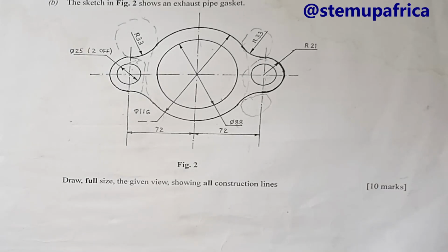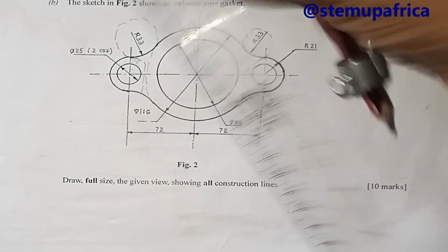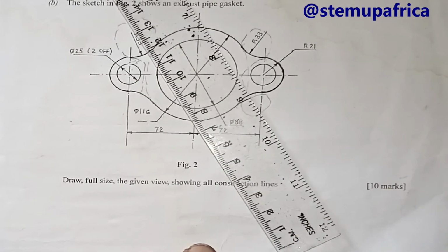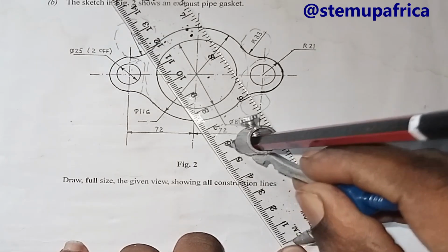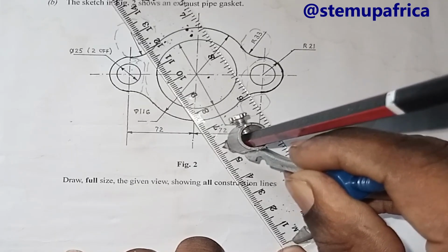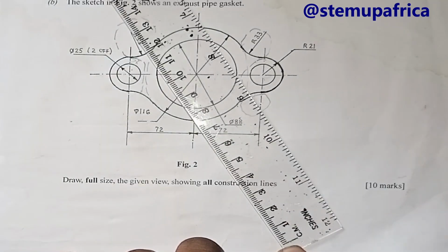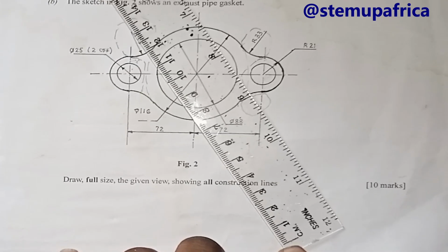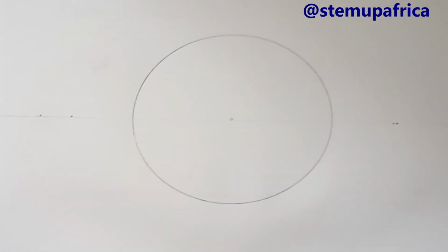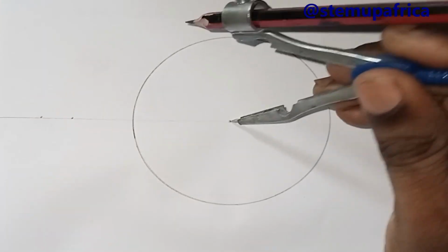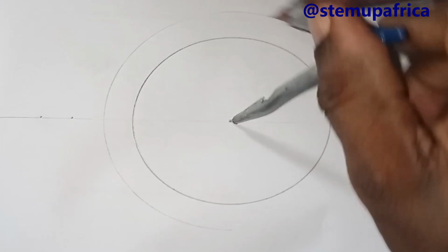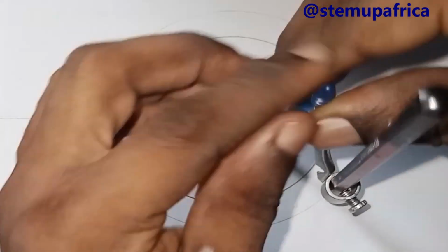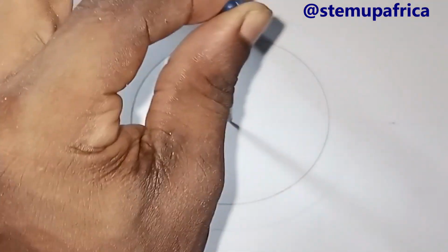So I will draw another faint circle. This circle will not be thick because it's not complete. I'll make it a faint circle of radius 58. After 50, close to 2 points before 60, that is 58. So I will draw a circle of radius 58. Let's draw a faint circle, not a thick circle this time because it's incomplete, of radius 58. I will just use a pencil without applying too much pressure. That will give me a faint circle of radius 58.